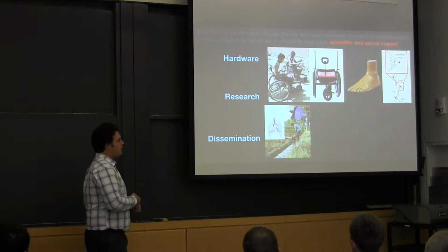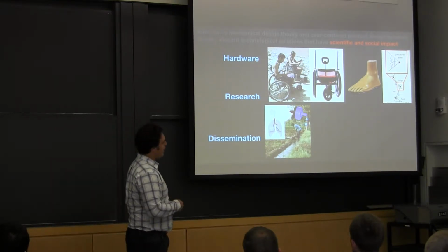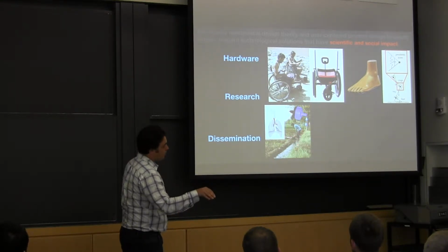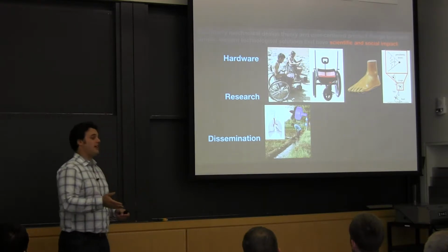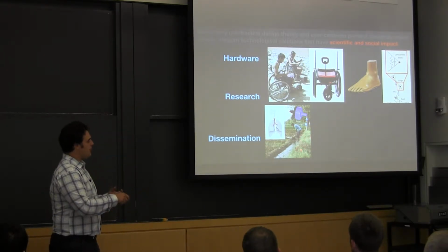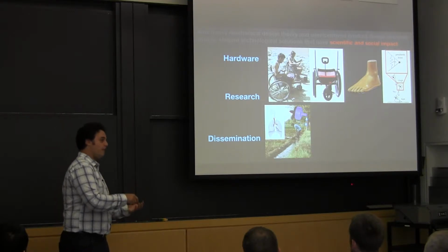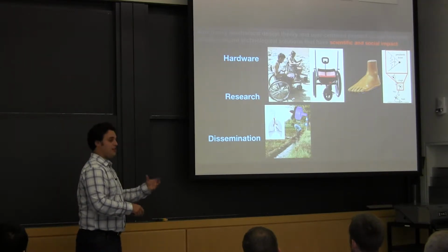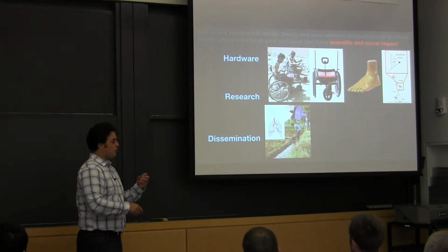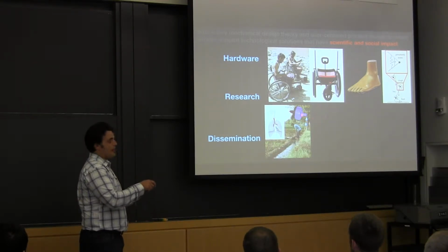We're doing drip irrigation systems instead of using flood irrigation, which you see in this picture. Drip just drips out the exact amount of water you need and requires about 60% less water than flood irrigation. But to do that with low enough pressure and low enough power to make an off-grid system economically viable for a poor farmer, we have to make it low pressure, and we have to make these things regulate water really accurately.